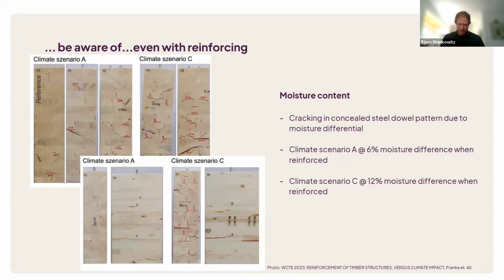One thing to be aware of, and you probably heard this, and I'm jumping a little bit forwards here, reinforcing timber. Some of you might have heard it already, and there are some thoughts around whether it's actually beneficial to reinforce timber against moisture, because at some point the stresses are even too high for the reinforcing. However, in recent tests, it shows that if your timber moves between 6 and 12%, 6 already starting to get critical, 12 being an absolutely doomed scenario, and you have your connection installed, there's likely something happening to them. So is it to the timber. Some of it might be at 6% only visual and not appealing, and you need to fix it, which is referred to as checking. And then it becomes structural, and then it becomes cracking.